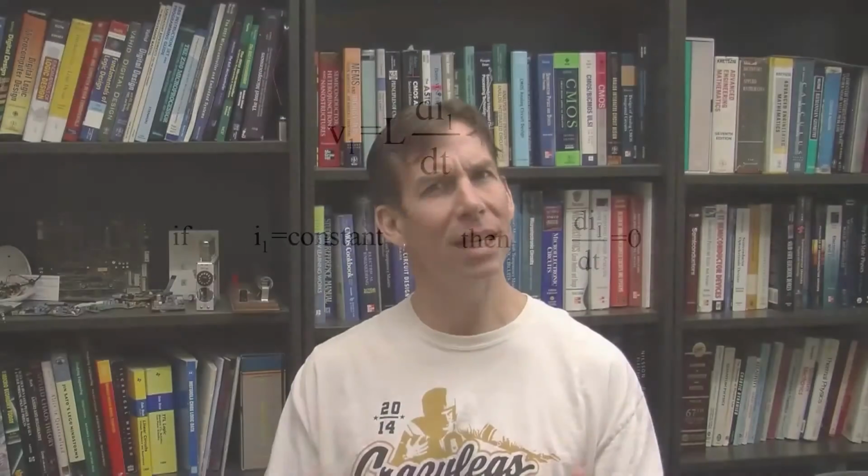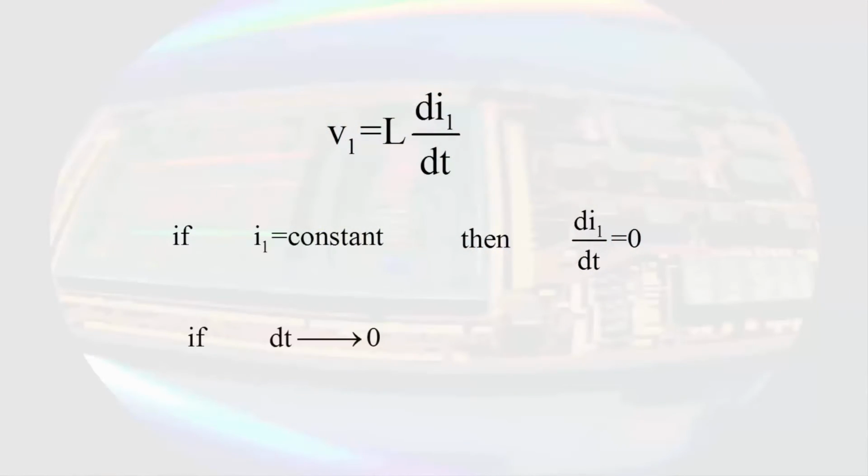Like with the capacitor, the current voltage relationship for an inductor is differential. However, the voltage is proportional to the derivative of the current with respect to time. This means that if the current through the loop is constant, the voltage across the inductor will be 0. This should make sense to us since the inductor is a wire, so when everything is in equilibrium, it should look like a wire. We can also see that if the current changes quickly, with the extreme being illustrated by the time interval going to 0, the derivative of the current with respect to time becomes infinite. Infinite voltage would likely have made Tesla happy, but cannot exist. An infinite electric potential would arc through the entire universe.